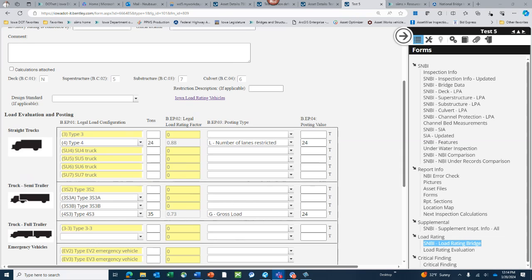Right. So the only things that I would say we are requiring now are making sure that you have your condition ratings in SNBI, so that the dates will determine your next inspection. Having the dates and your ratings in there will tell you whether you have to go to a 12-month inspection, or underwater if you have to go to less, or to track when your 24-month inspection would be due.